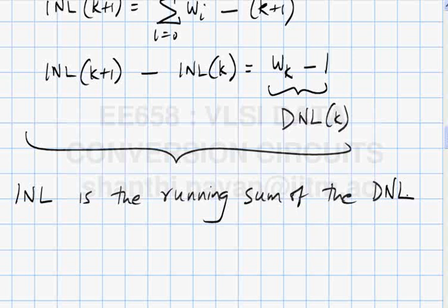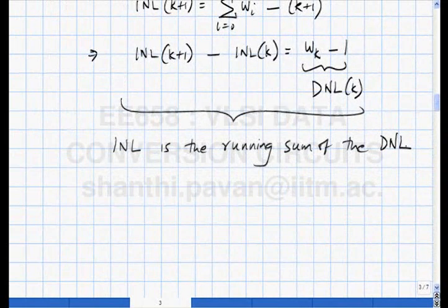Whenever you pick up an ADC data sheet or when you are reporting a new ADC, the measurements you show come under what are called static measurements. That is, if you put a sufficiently slow ramp into the ADC, the output will look like a staircase, and the shape of the staircase is what you are showing. As I kept telling you earlier, it doesn't make sense to say the width of my kth code is 1.01 LSBs. Everybody knows you are supposed to get 1. So what is of interest is the difference between the obtained code width and the ideal code width.